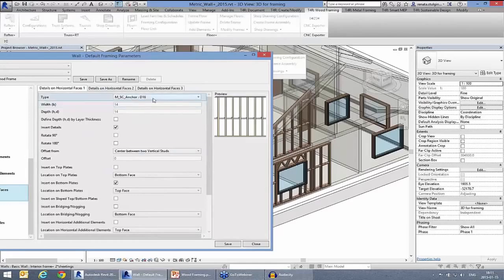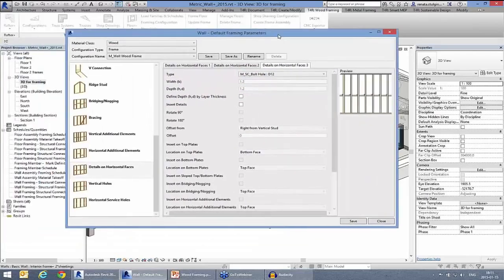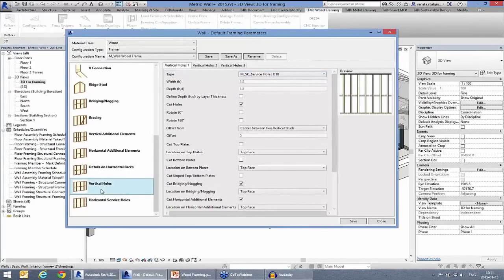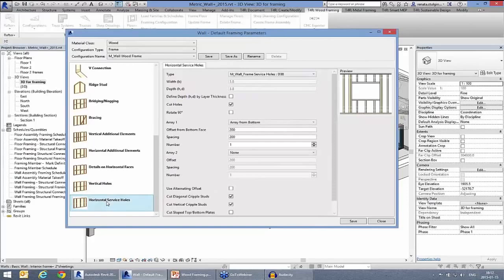In my example, it was an anchor that was added on the bottom face of my element. Then the angle families, and also the bolt holes could be added. Those families are our sample families, but you can also choose your own. And then the settings for this vertical.